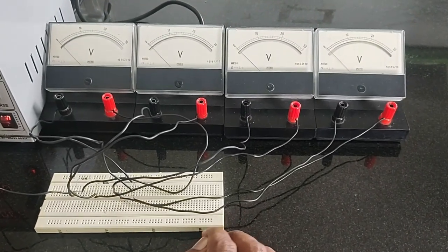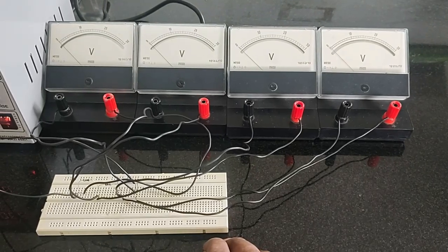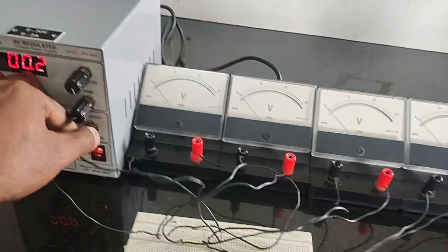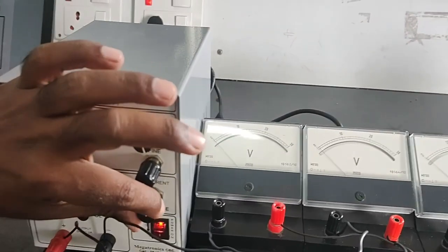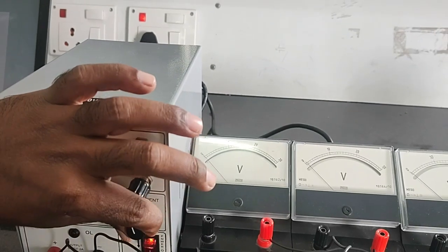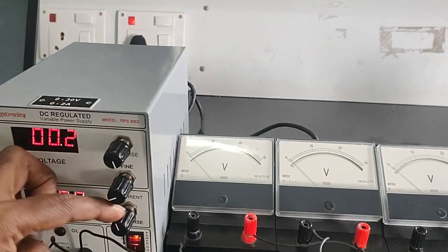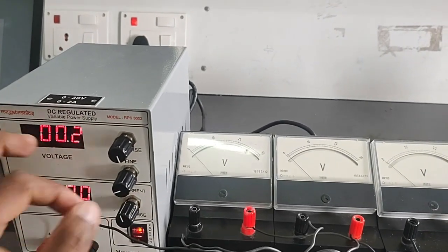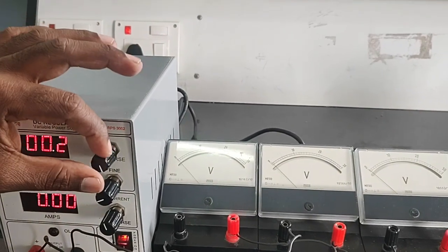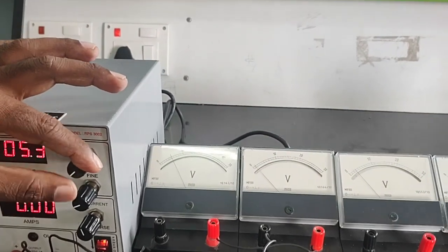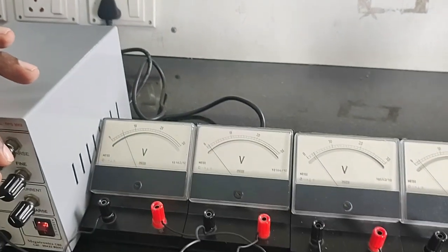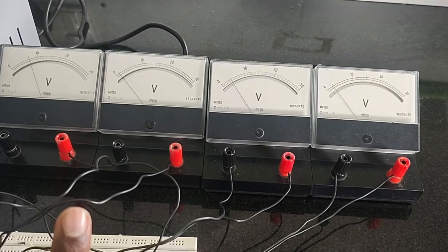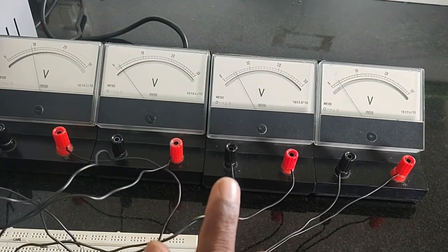Now we are going to verify the Kirchhoff voltage law. Always in the RPS we have to keep all the controls at minimum. Then in this RPS, first of all we have to set the current to maximum, so using the knob we increase the current to its maximum value. Now gradually increase the input voltage. At the same time we have to verify that all the voltmeters indicate some value, by using the voltmeter readings.